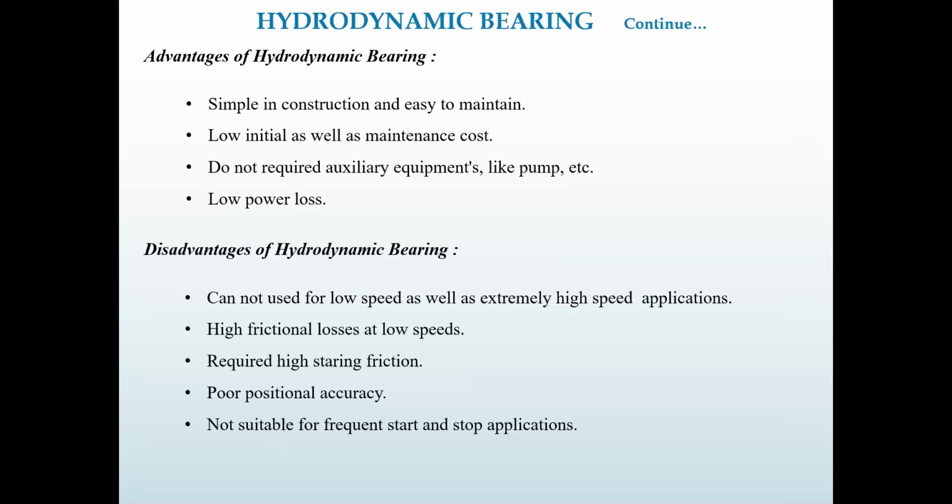Now the disadvantages: at the initial condition the friction is very high. That is a big disadvantage of the hydrodynamic bearing. We cannot use such bearings for low speed applications as well as extremely high speed applications. As we saw, at low speed the frictional losses are very high, so it requires very high starting torque, or you can say high starting friction.